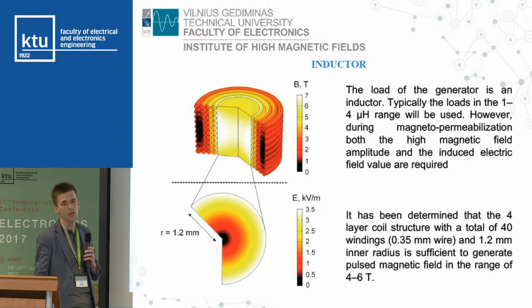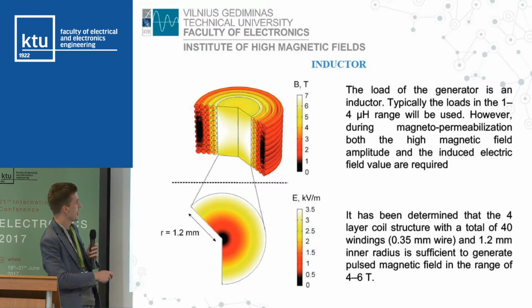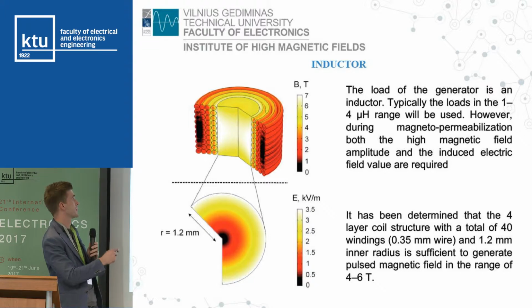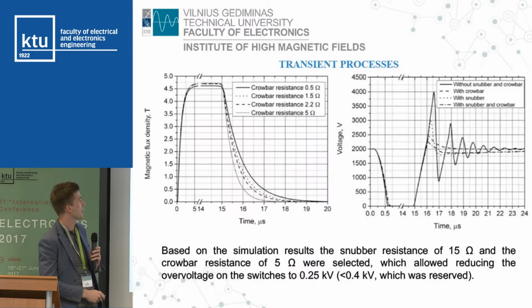And actually, right now, we have a well-developed mechanism for why it happens and how cells react differently both to the magnetic field and to the induced electric field. So basically we have 2 responses during one pulse. In this case, our generator had up to 4 microhenries, and with 900 amperes, it could generate something like up to 6 Tesla. But this is model data, simulation.